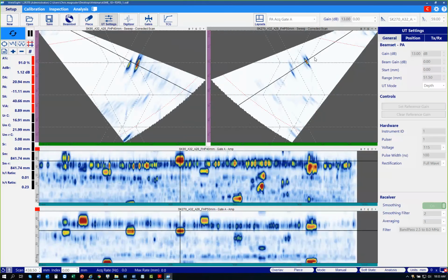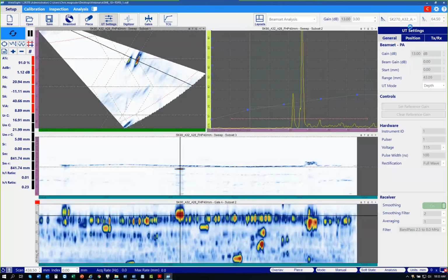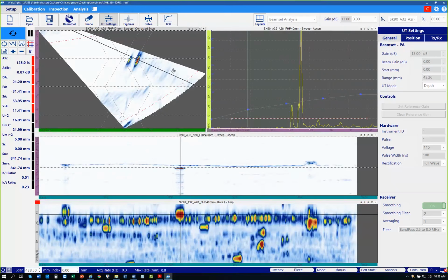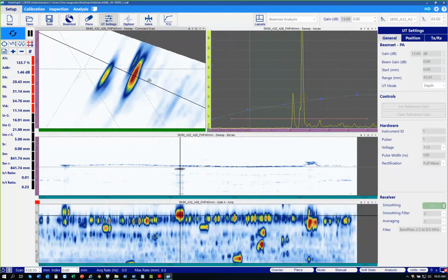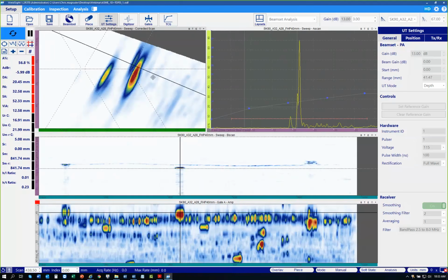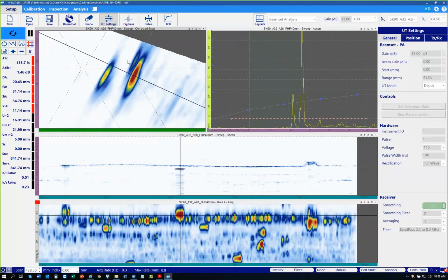So I'm going to move to a single beam set layout on the 270, and I'll characterize that in the B-scan here, and we'll size this flaw. Again, the amplitude does not play a big role in this sizing, and had we not been able to get a tip, like the example we'll see later, this would just be a close estimation of that flaw's size.